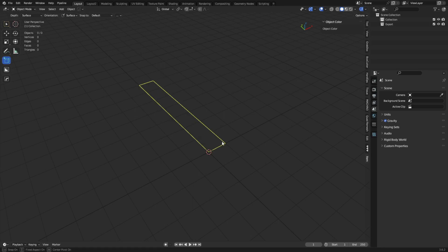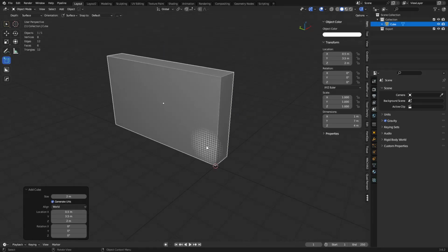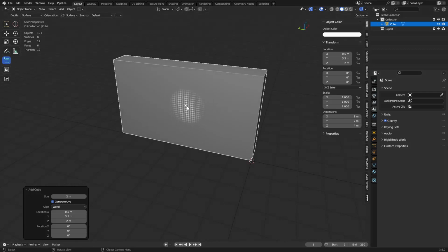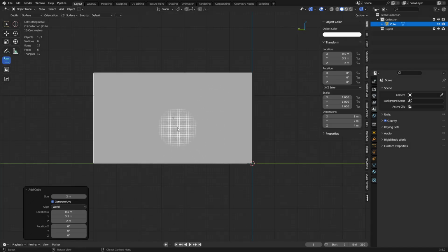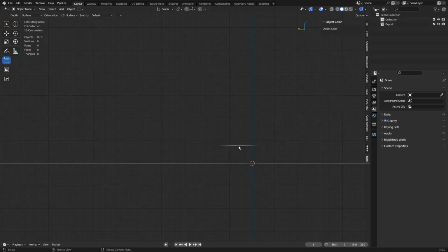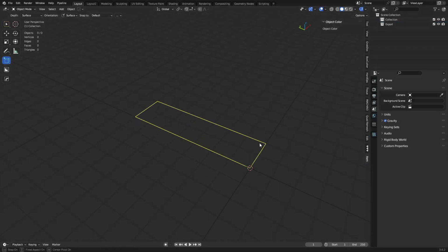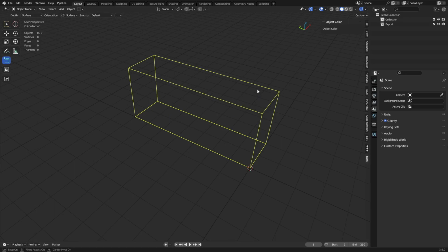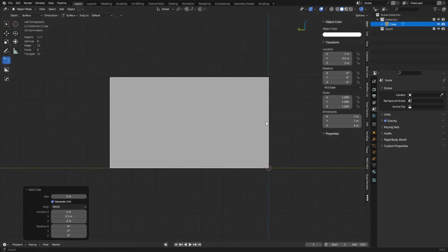There's a little trick to this thing, all right? So if we drag out a section and we start bringing it up, when you're creating modular pieces anyways, generally speaking, a center alignment like this doesn't usually work out too well. Because in this example, we have a 1 by 7 by 4 meter shape here. So this is right in the center here, and it won't snap to the 1 meter increments. All right, a little bit of a problem. So it really likes to be done in twos, so by 2 meters maybe. That's why using a half meter might not work out too bad for you.